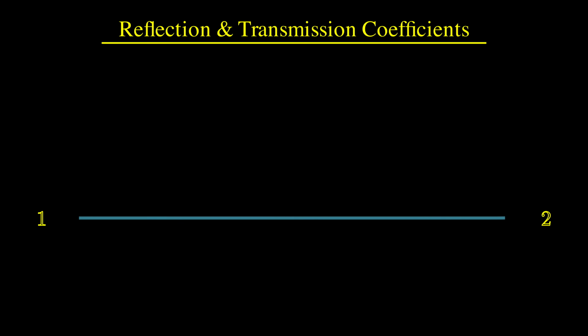Now that we've covered the fundamental theory behind S-parameters, let's try to examine and interpret what is actually going on inside a network upon the instance of an input wave. If the two ports are perfectly matched, the signal will not stumble upon any discontinuities or mismatches, and no amount of energy will be reflected.